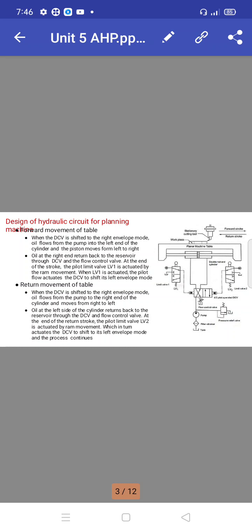It may be used to bring the oil back to normal temperature. That's why we supply it to the reservoir. When we actuate something, the hydraulic system gets heated, and that should be overcome, so the oil is sent back. Whatever hydraulic fluid we use should be transferred to the reservoir and recirculated. That's how the temperature is maintained constant.